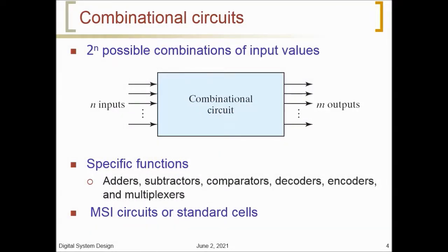First of all, we discuss combinational circuits. A combinational circuit consists of input variables, logic gates, and output variables. Combinational logic gates react to the values of signals at their inputs and produce the values of the output signals, transforming binary information from the given input data to a required output data. A block diagram of a combinational circuit is shown in this figure.